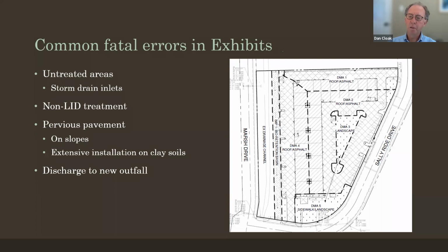And so the proper pervious pavement on a clay soil for a road or driveway or even a parking lot is generally going to require a very deep section, which is going to require a lot of excavation, potentially a lot of off-haul, a lot of backfill with base course material, and then the pavement on top of that.